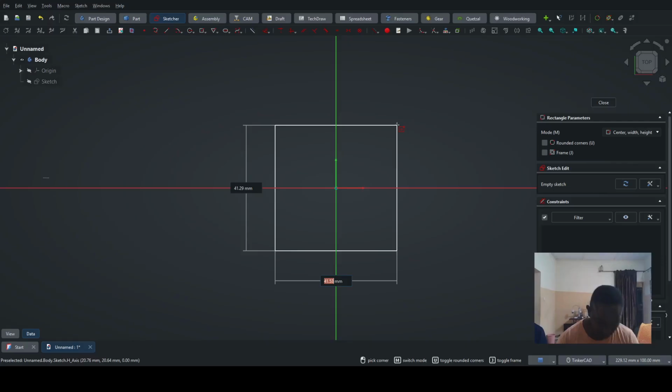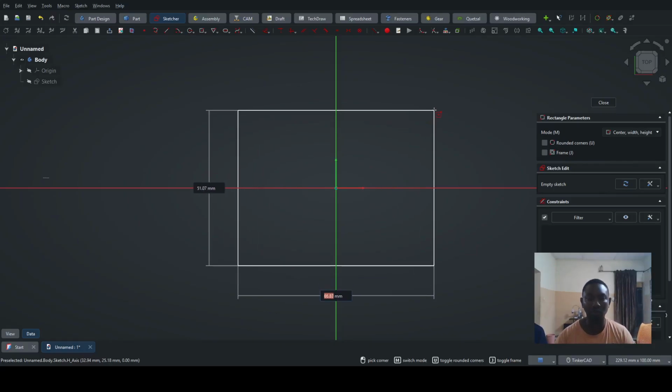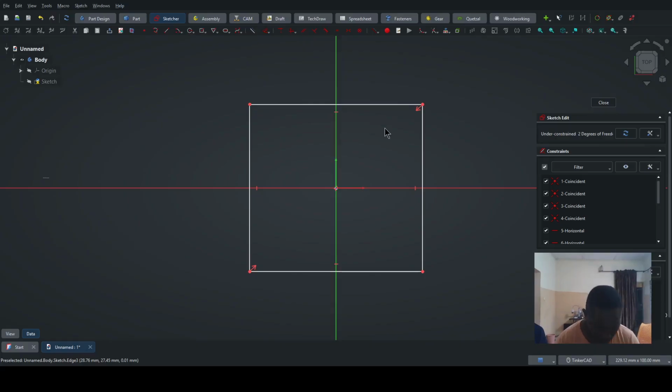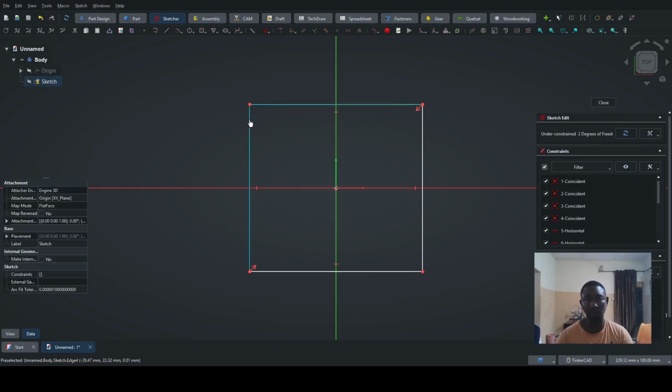Let's put in our basic dimensions, which we can always adjust later on. But I think let's do it this way. Let's first of all draw the basic rectangle. Let's leave it like that. We'll put dimensions later on. Now, I want to teach you how to form curves or fillets or arcs around your basic drawing. So I can select this line, and go and do this. You see, this is called the sketch fillet tool.